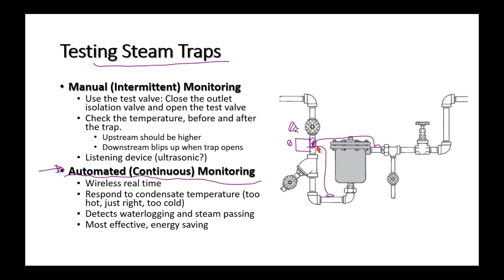Okay, and so if you're sitting in the control room and you wirelessly address all of these different steam trap monitoring stations, it'll tell you, is my steam trap waterlogged? Is it passing steam? Is it working correctly? And now you can pinpoint exactly where to direct your maintenance dollars. And I tell you, it's real time. It is effective, and it saves energy.